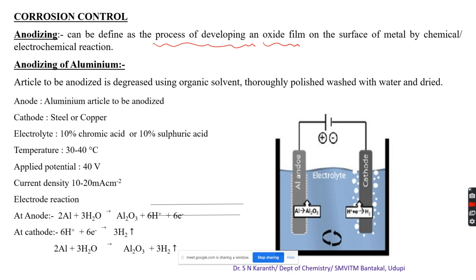That means to carry out that process, we have to apply a particular voltage of potential. If it is more, almost all the metal gets dissolved. If it is less, then less dissolution takes place, and it is difficult to get the desired thickness of deposition. So that's why we have to introduce a suitable potential, and we have to take a suitable